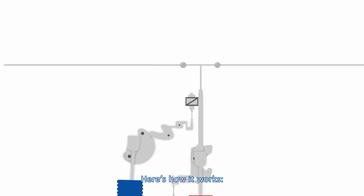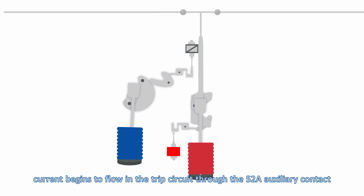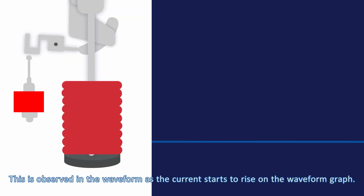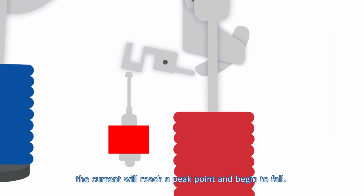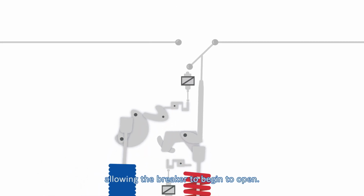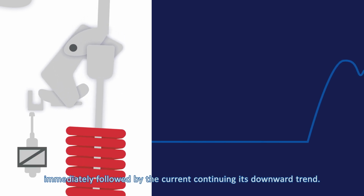Here's how it works. As the breaker is called on to perform a trip operation, current begins to flow in the trip circuit through the 52A auxiliary contact and a plunger begins to be pulled through the coil. This is observed in the waveform as the current starts to rise on the waveform graph. Once the plunger has achieved maximum velocity, the current will reach a peak point and begin to fall. This decrease will continue until the plunger strikes the latch, releasing the breaker's stored energy, allowing the breaker to begin to open. This is visible in the waveform capture as a momentary rise in current immediately followed by the current